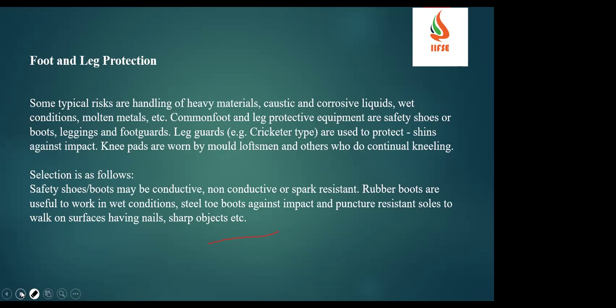And common foot and leg protective equipment are safety shoes or boots, leggings, foot guards and leg guards, etc. And knee pads are also used. And if you see the selection, the safety shoes and boots may be conductive or non-conductive or spark resistant. Rubber boots are used for work in wet conditions, and steel toe boots against impact, and also puncture resistant soles to prevent injury while walking on surfaces having nails and sharp objects.